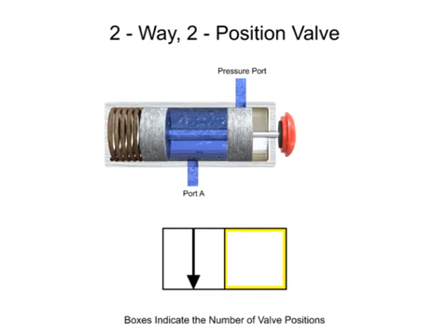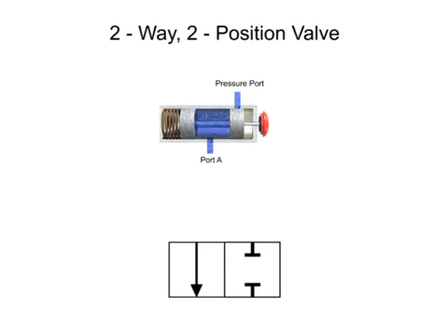The second box corresponds to the second position of the valve. Therefore, 2 T's are added to illustrate the lack of fluid flow in the second position. Next, lines are drawn to indicate the normal position of the valve. The normal position is defined as the position of the valve when its spool is unshifted and the power is off. This means that any mechanical actuators, such as springs, are in their non-actuated positions.